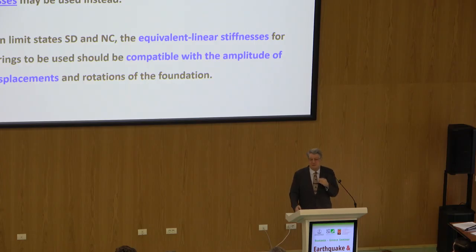Where can we use frequency independent stiffness? Guys, we cannot do dynamic time history analysis. Frequency dependent stiffness, yes, you can use it. But at what period? At the period of the fundamental mode. Totally clear with you. The fundamental mode of the soil, natural period. If you cannot find this fundamental period, use the static stiffnesses. So, simple ideas like this are continuously written in the code if you try to read it.